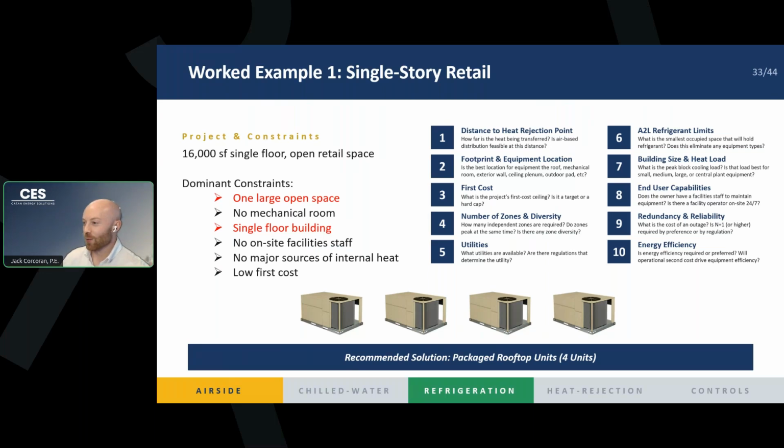If you can use rooftop units, these are super cost effective. They work great for places where you don't have huge heat loads and you don't need a lot of maintenance. It's just install it and forget about it, and it works great. Because it's a single floor building, the roof is a great place to put equipment, and it's one large open space. We don't need to worry about zoning it out. We don't necessarily need an individual unit in every room because it is just one large room. So if we stick rooftop units on the roof, we're just going to need ductwork, a crane to lift them onto the roof, and a thermostat on the wall to control it.